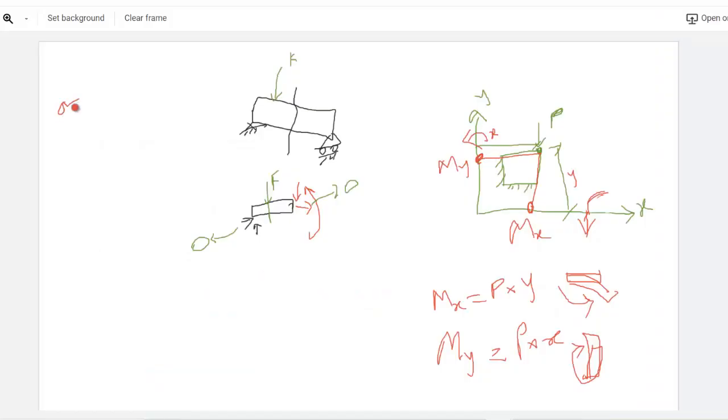So we know stress is sigma equals force over area, right? So this normal stress is how many types? Two types. One is compression, one is tension. If you find this is acting like this, this is the compression. If you find this is like this, this is the tension. So due to the tension force, it will be tensile stress. Due to the compression force, it will be compressive stress. So these two are the normal stress or the axial stress.